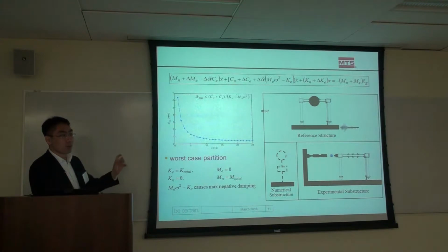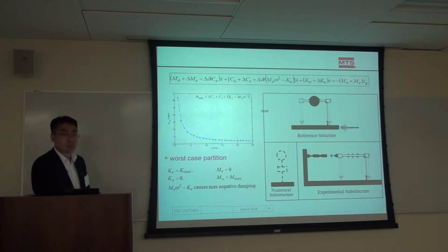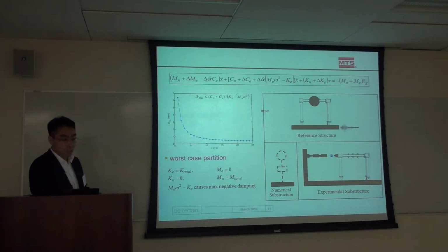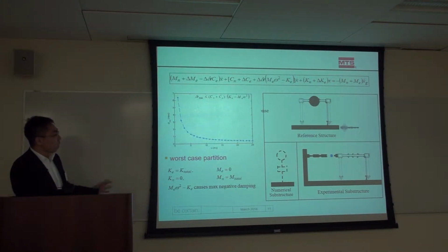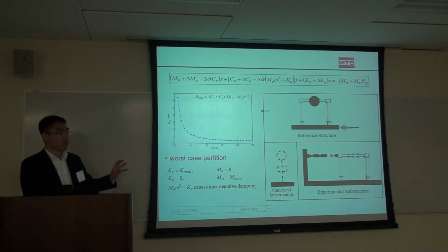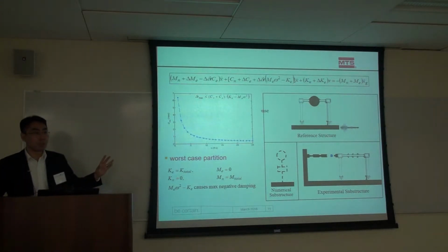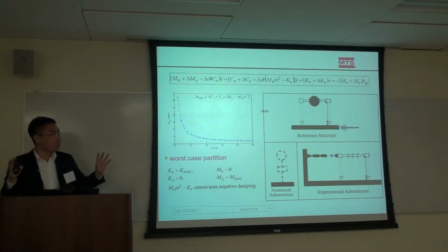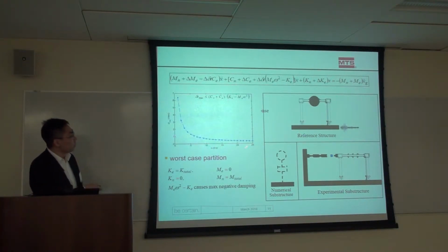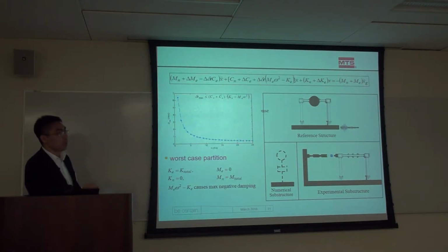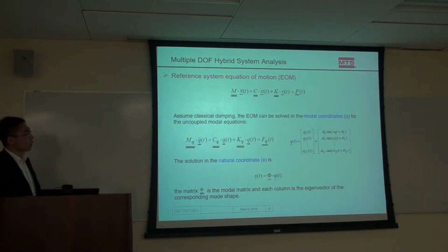1 millisecond is actually our controller clock. So you have to beat that controller clock. You can pretty much get a perfect control in order to make this real-time hybrid system just stable, not to mention performance, right? So I hope you can get that concept. So first, when you design your real-time hybrid system, do the substructure partition, think about how you want to divide your substructure. Don't get into somewhere you have to go to this region, then you have to get an extremely accurate control, and that's very, very challenging.